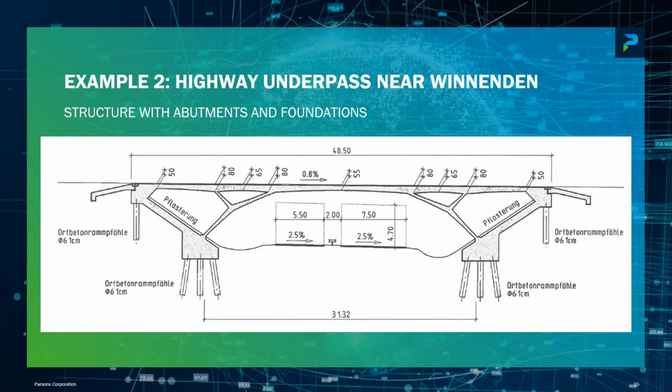Now you see how this bridge actually works, because the soil didn't allow us to transfer the horizontal thrust of the arch to the soil. So what do you do when you want to build an arch bridge but the soil isn't adequate? Then you think this over and create not an earth-anchored system, you create a self-anchored system.